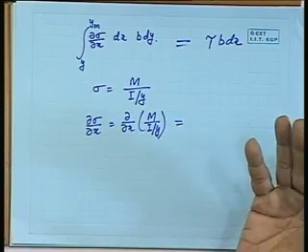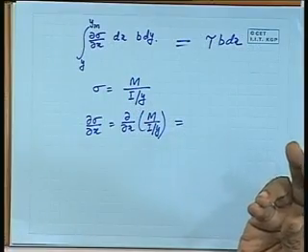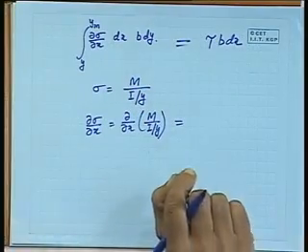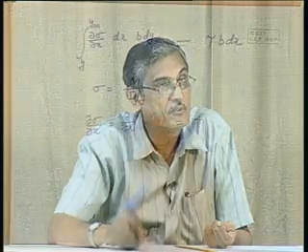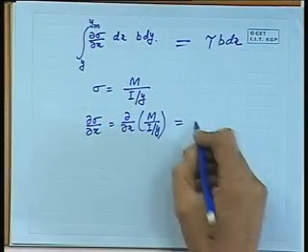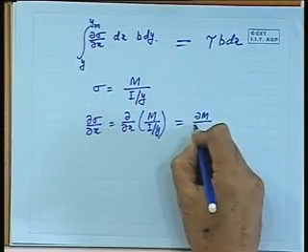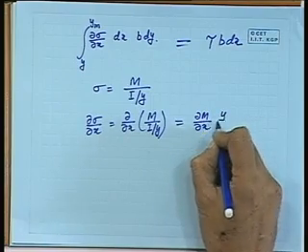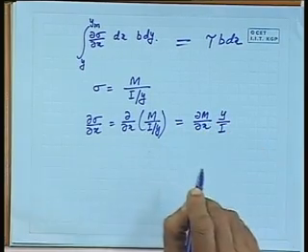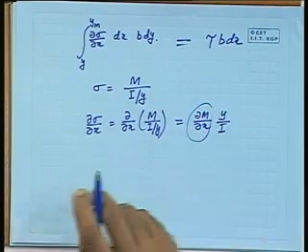Now I is constant of that particular material, and y we have assumed at a particular layer. So y location is also fixed. So it is only M which is varying with respect to x, and therefore this will be dM by dx, you can say y by I. What is this quantity dM by dx?